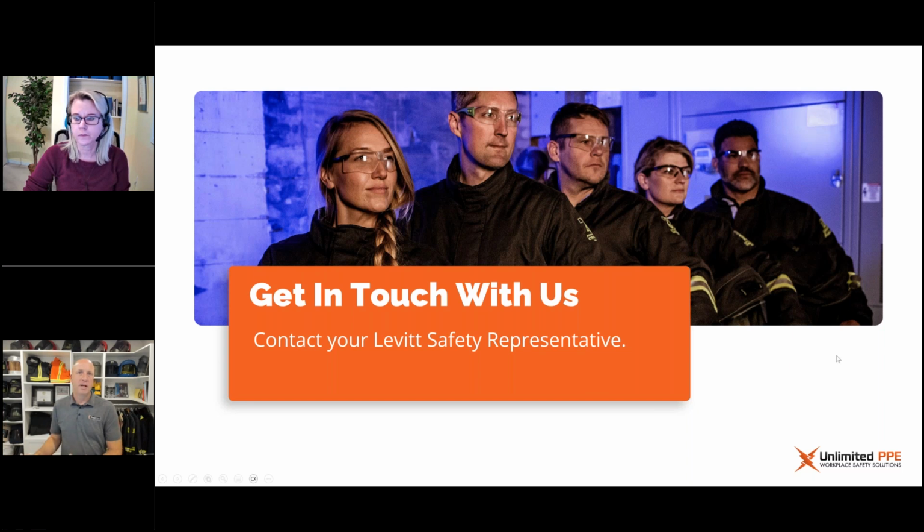So the process of de-energizing, if there is a threshold that's been passed for when an arc flash hazard exists, you would then still need to wear arc flash PPE to verify absence of voltage. So first you have to ask yourself in the risk assessment, does an arc flash hazard exist?